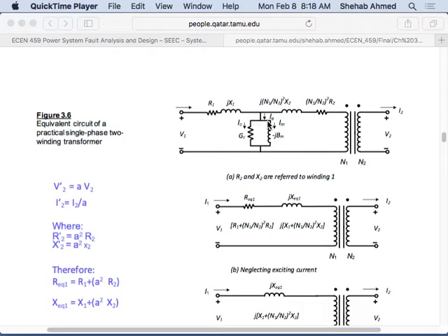Okay, so do I do that on the primary side or the secondary side? Let's look at the open circuit test. If this is a step-down transformer, high voltage side, low voltage side, where would you want to perform your test? High voltage side is high voltage, low current. Low voltage side is low voltage, high current. So to do the short circuit test, I think it's better to maybe use a lower voltage source and have lower short circuit current, right?